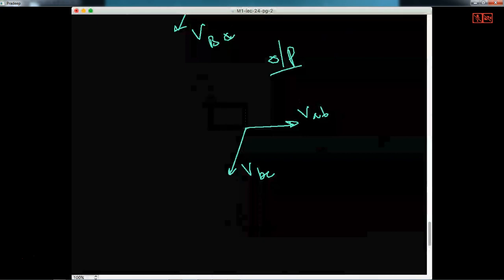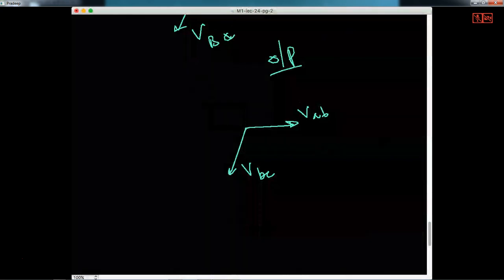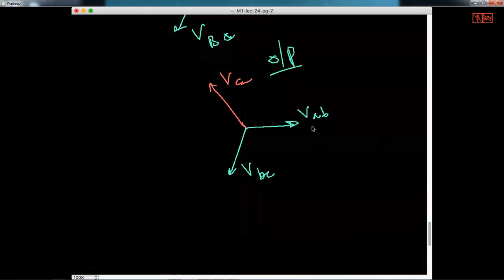So this is VCA. So this is the output voltages. So even though one of the legs is not there, still the transformer can work based on only two phases or two windings. But the only thing is the capacity is reduced by 57%.